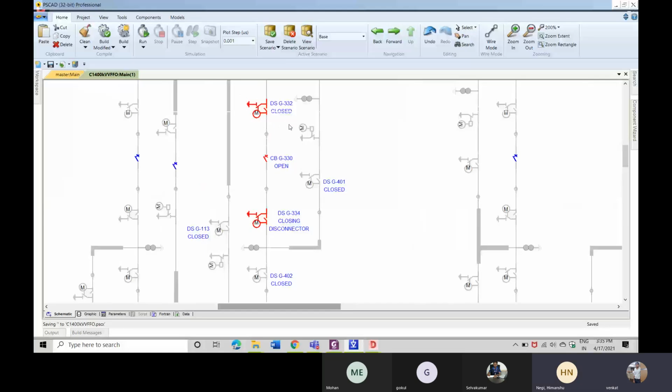Then what we have to do is close this disconnector while keeping all the other side open. Then only the current won't be passing, right? You got that point. For that, I have made this disconnector close first, and only then will your circuit breaker be closed. I hope that point is clear for you. Say again, when will the disconnector be closed.